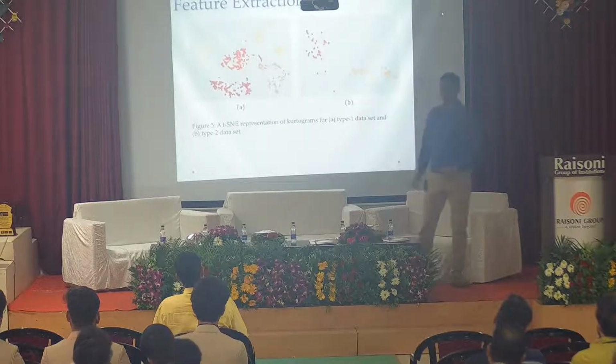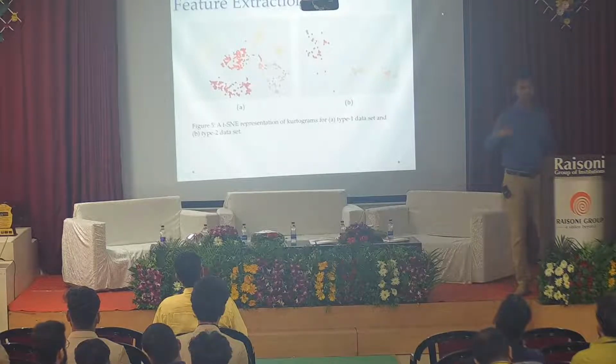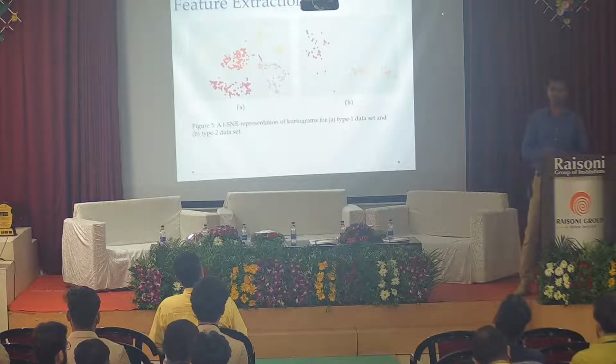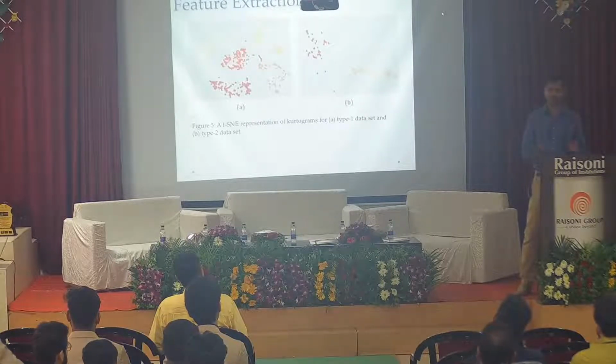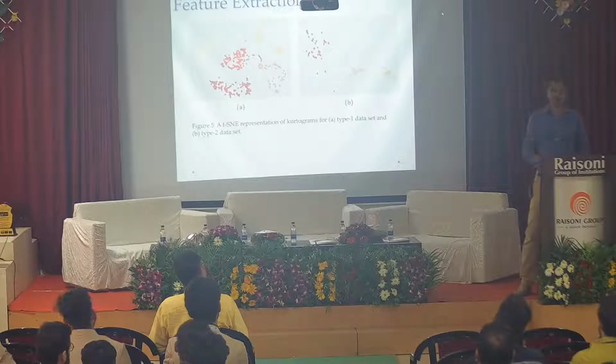This is for CWRU. There are different techniques, but this I have used. Basically, whenever we transform the data into an image, we check the t-SNE embeddings so that we get a two-dimensional representation, and we get confidence that we are going in the proper direction. If not, then we have to rethink the transformation. Whatever transformation we have done, we have to rethink the design aspect or change that part. So next slide please.